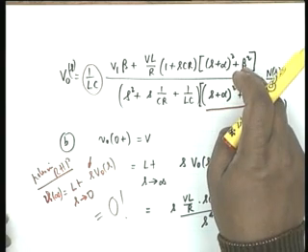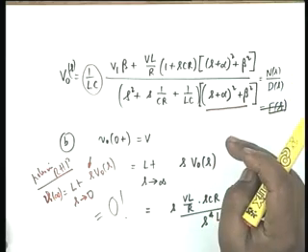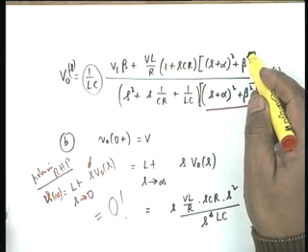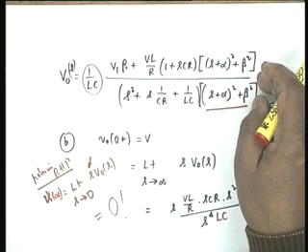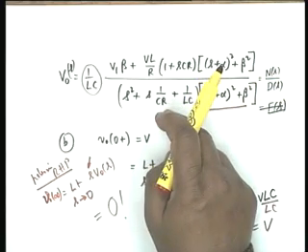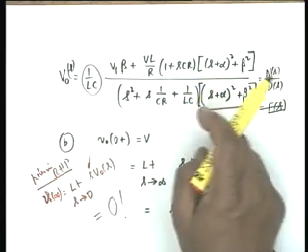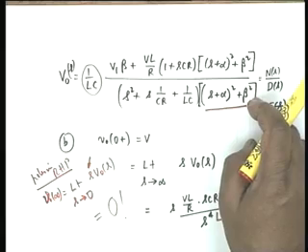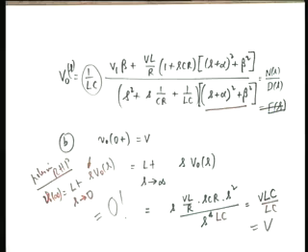It should be possible to say this by inspection. This is a cubic polynomial. When we multiply by S, it becomes a 4th degree polynomial with the lowest power term equal to some constant multiplied by S. In the denominator, it is also a 4th degree polynomial. The constant term is 1 by LC multiplied by alpha square plus beta square, and therefore when S goes to 0, the numerator goes to 0, the denominator remains a constant, and the whole thing goes to 0.